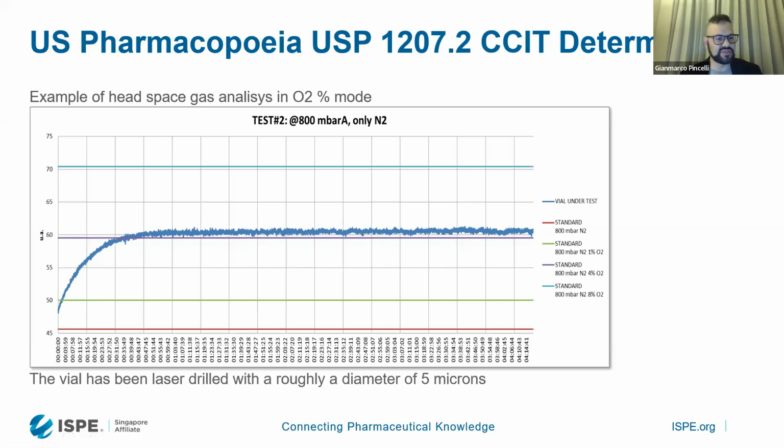As you can see, starting from the point zero as well here, in this case, we are measuring the oxygen. So oxygen should be absent inside of the product, but if you have a leakage, some atmospheric air with oxygen is entering the product. As you can see, after 15 minutes, we can say we had a really good separation, and after 40 minutes approximately, we get 4% of oxygen, because as well here we made standards. The violet line was 4% of oxygen.